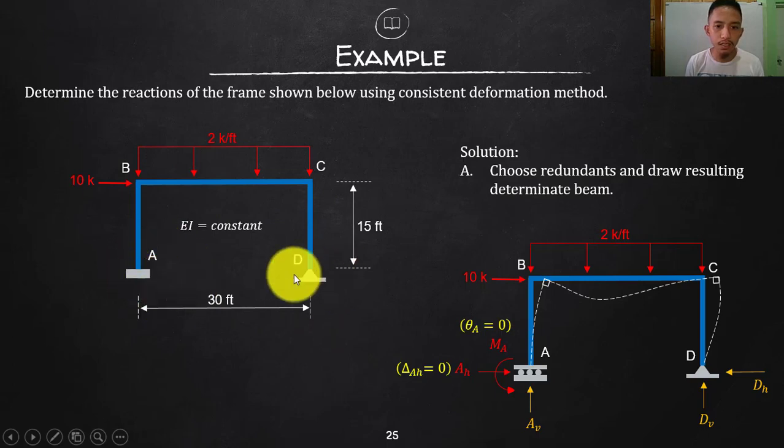Once we get the reactions here, this is a simple frame, so you can just cut it and bring out the forces or solve the internal forces. Then you can draw your shear and moment diagram. Actually, please do not interchange your truss and frame. In a frame, there is a moment on the member itself, while in a truss, there is just tension or compression in the members.